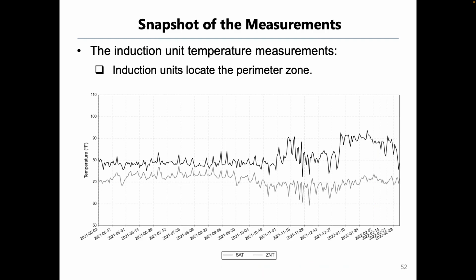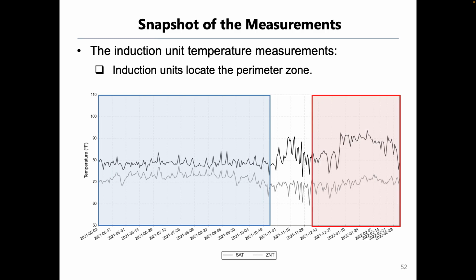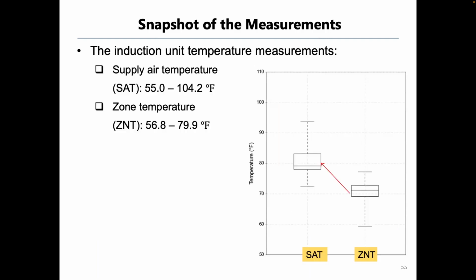In the induction unit, as I mentioned earlier, the induction unit takes the heating part. During the summer season, there's no heating or cooling operation from the induction unit. However, in the winter season, there's a big gap between the supply temperature and the zone temperature. That's why the induction unit usually takes responsibility for heating the space.